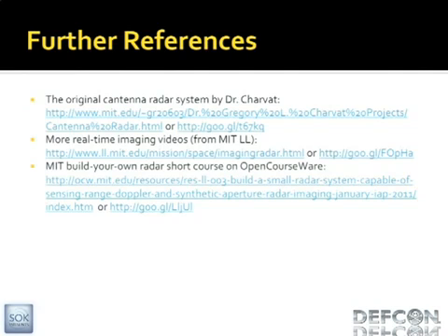To some extent, for the SAR stuff, we want something a little less directional than that. Part of it is that the coffee cans were what was available at the time. So MIT students drink more coffee. Well, that's probably true. We could graph that. But yeah, it's pretty open. You basically get different characteristics. If you're trying to do the SAR imaging, having a wide beam width is actually somewhat useful, because it decreases some of your spatial fidelity, but you also get a wider image. If you have a very narrow beam, you're not going to get any signal from something that's further apart. So it's a trade-off there.